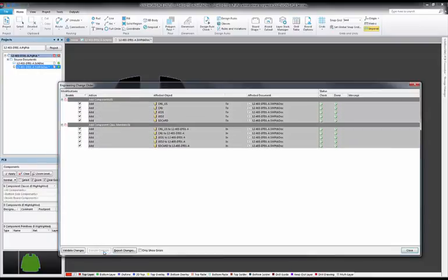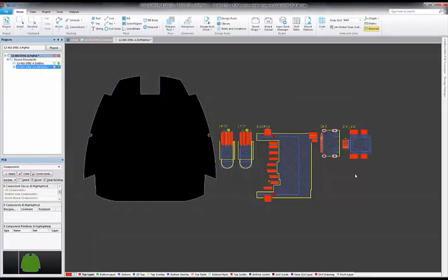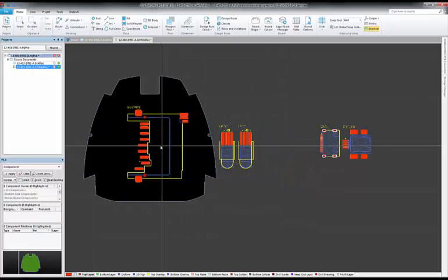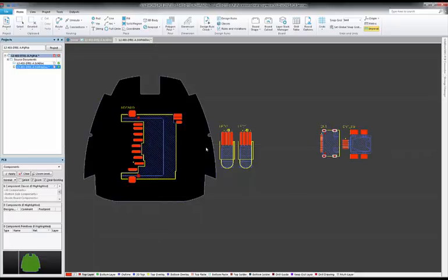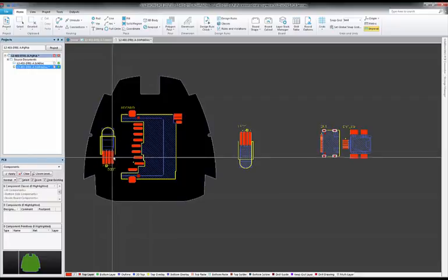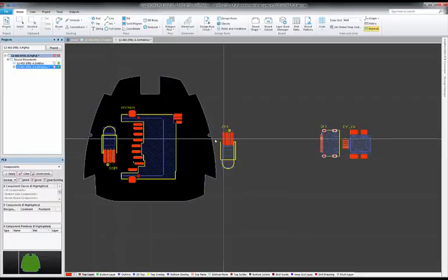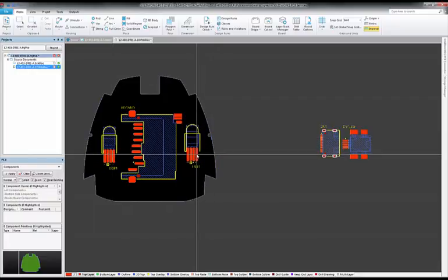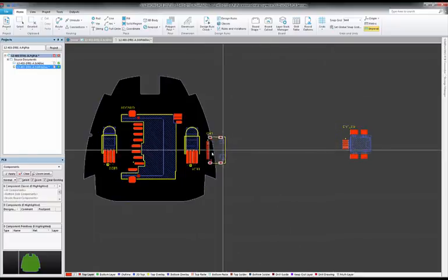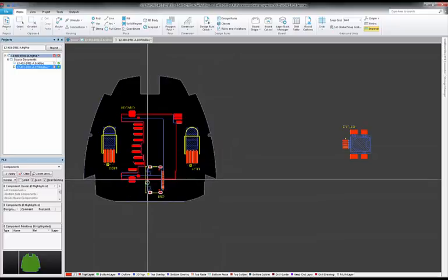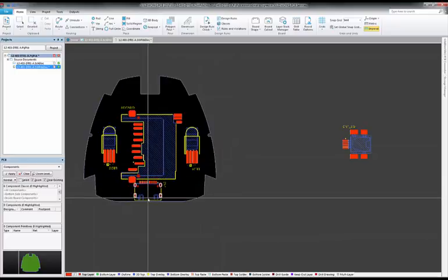At this point, we can read in our components from our schematic and begin initial placement. Place the components that have a requirement from an enclosure, interface, or other mechanical requirements perspective, including our connectors. And once we have those components placed within